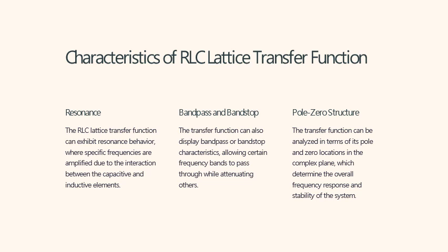Bandpass and bandstop. The transfer function can also display bandpass and bandstop characteristics, allowing certain frequency bands to pass through while attenuating others. Pole-zero structure. The transfer function can be analyzed in terms of its pole and zero locations in the complex plane, which determine the overall frequency response and stability of the system.